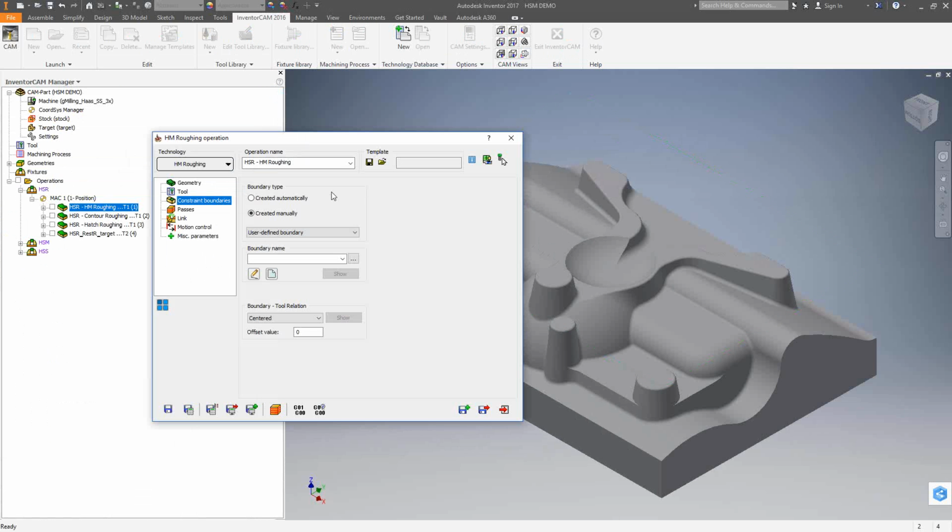area. Once we decide what area we would like to fence off or just kind of machine only in that one area, we can decide what type of boundary it is here. And in previous videos, you would have seen this. It's external, internal, centered, and tangent. Essentially, we will machine what's inside of the contour, but we'll reposition outside that contour or stay within that contour depending on which option we select here. For a review on that, I would refer you to the 3D iMachining video. So like I said, we'll just go to create it manually.